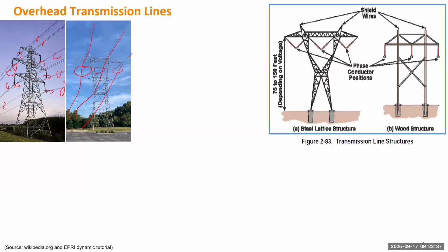And for this, the left tower, you have 6 insulators, so it actually carries 2 sets of transmission lines, and each set has 3 phases. But if you count how many wires in the first picture, you see maybe 1, 2, 3, 4, 5, 6, but on the top, you also see a few wires. So the top one is not a transmission line. The top wires are called the shield wires.